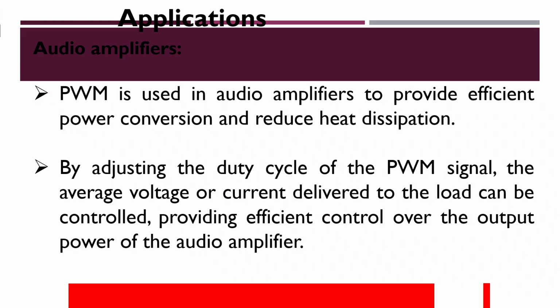So how do you write a program in embedded C for this? The PWM should be identified with PWM underscore set duty cycle bracket 75. So the duty cycle may be 75%, so that 75% of the time the relay will be closed on the kit.